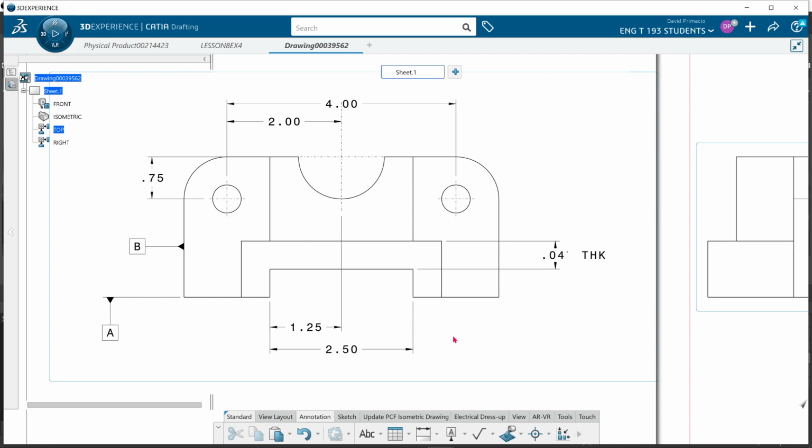That's up to you guys, but a lot of people get confused about why I dimension it like this. Why don't I dimension everything off the datum? The reason is because I'm not holding the tolerance the way I want to hold it if I don't dimension off the center. So again, when you create symmetrical parts, this is your better technique. Hopefully you can use this as an example on how to go ahead and finish the two drawings for these two details.